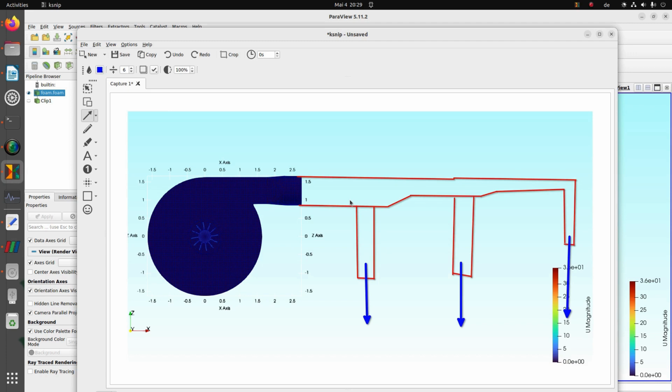This allows you to calculate whether enough air is flowing through the individual outlets, and if necessary replace the fan and or adjust the outlets so that the same volume flow passes through the individual outlets.